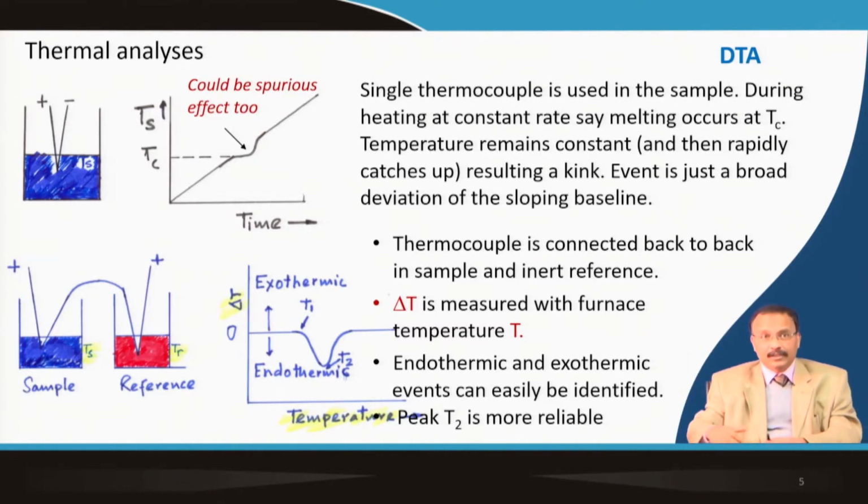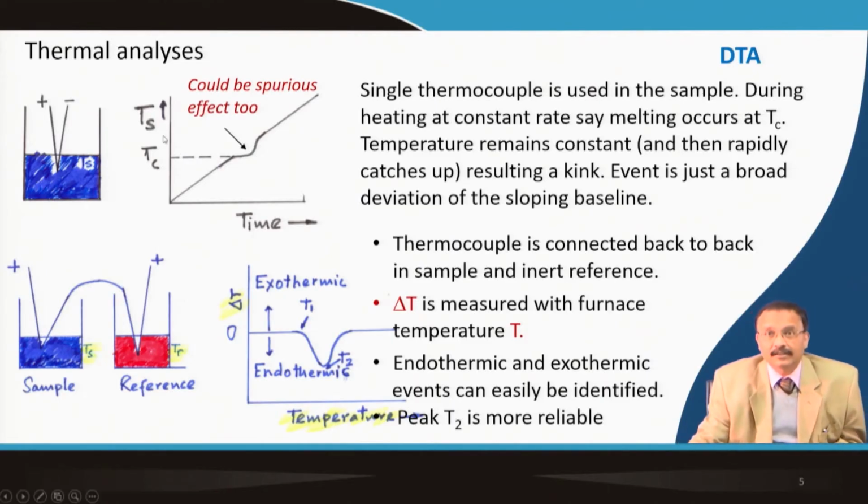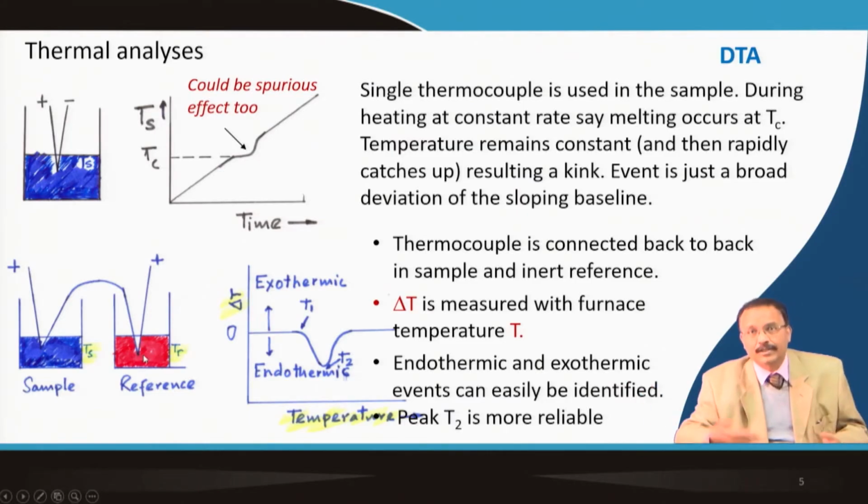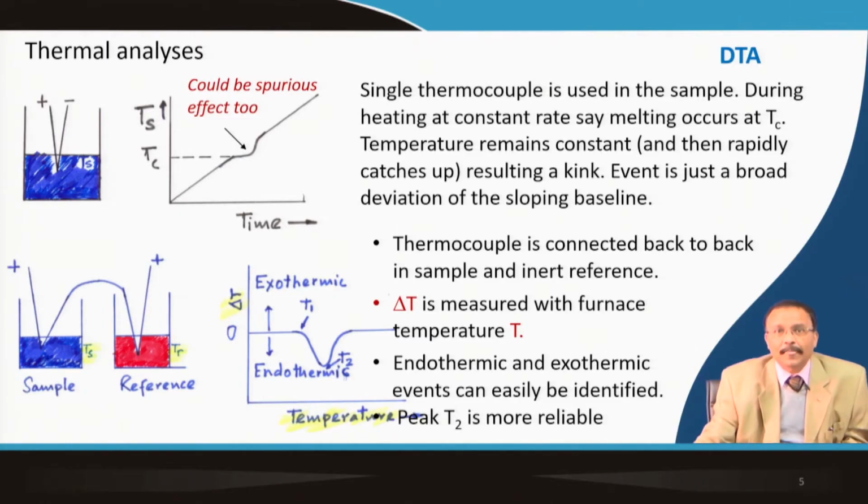Therefore, this differential thermal analysis is important, where you have your sample and along with that you have an inert material which does not undergo any kind of reaction, be that decomposition or whatever. No reaction is taking place, so it remains in its pure state; there is no phase transition, no polymorphic phase transition, nothing is happening to it.